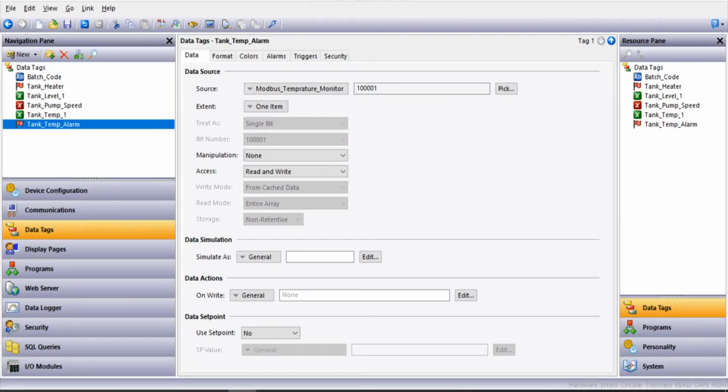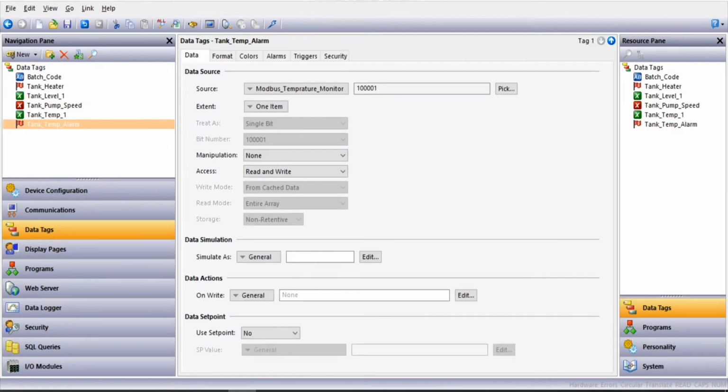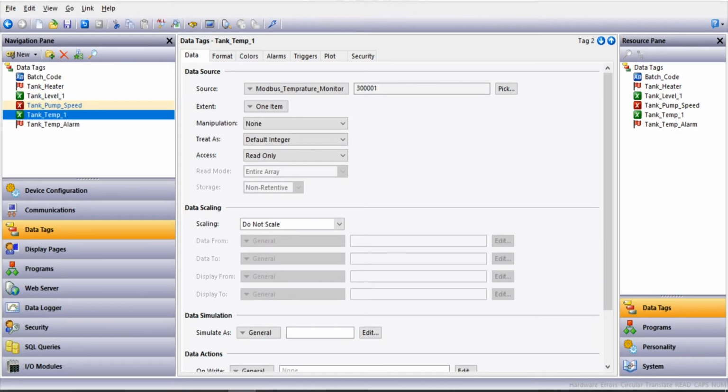So what we have is a project here to simulate a tank. We've got a number of tags that I've pre-made in here, and what we're going to do is basically log two types of log. The first one being a log every 60 seconds where we'll take the tank level and the tank temperature every 60 seconds and just put that as a history of what we've got, put it into a CSV file so we can access that later.